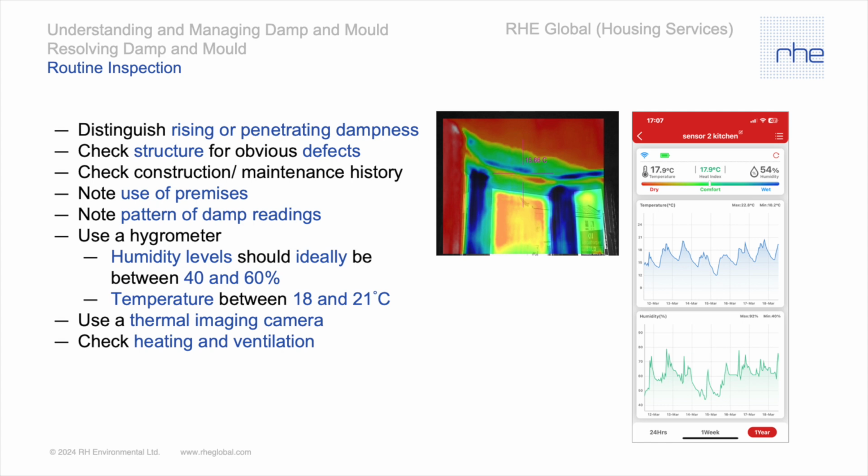If you're taking any damp readings, then the key features to look for would be whether readings occur towards the bottom of the wall or at the full height of the wall or just the top of the wall. And you're looking for any sharp drop-off between areas of high readings and areas of low readings.